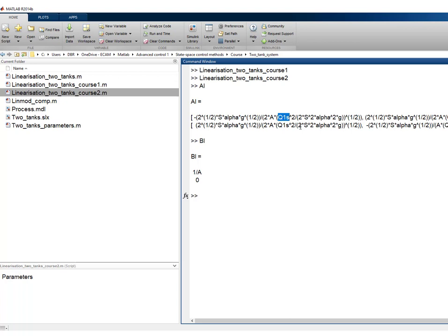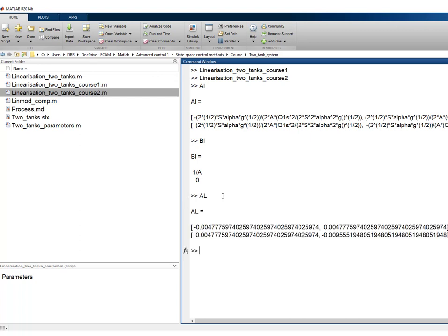5 liters per minute. In the slides, the state space matrix is written as a function of H2S, but of course H2S is itself a function of Q1S. So these expressions of the state space matrix are equivalent, and to see that, we can also have a look at what it looks like if you replace the variables by the expressions that we had used previously in the simulation.